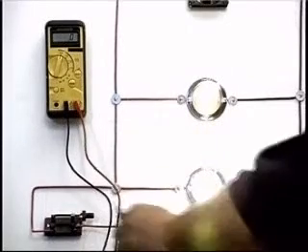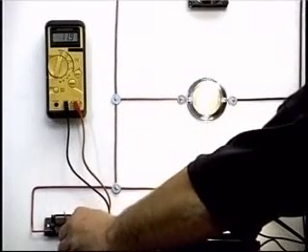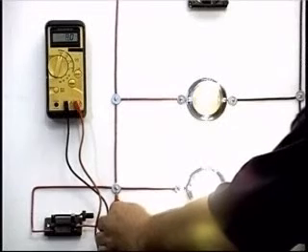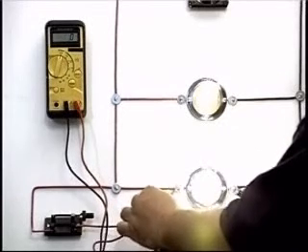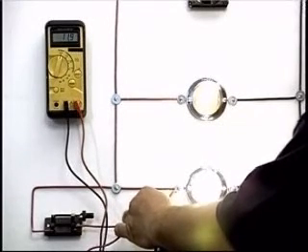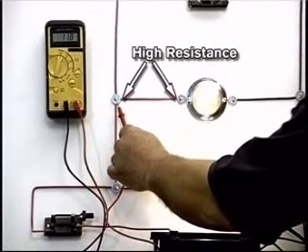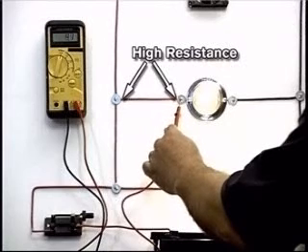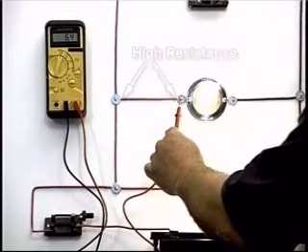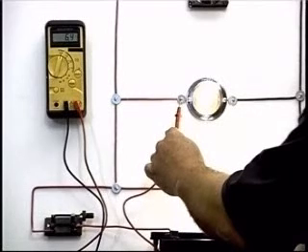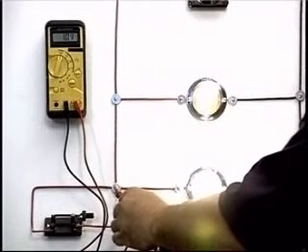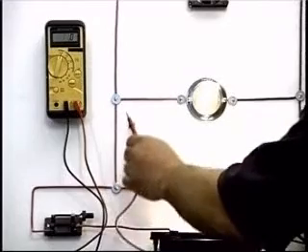Because the meter is attached parallel to the circuit, readings at any point between the positive battery terminal and the load should register full circuit voltage. However, if a high resistance exists in the circuit between the voltage source and test point, a reduced voltage will be observed between the resistance and ground. Taking readings at various points will allow identification of the resistance by narrowing down the section between normal and low readings.